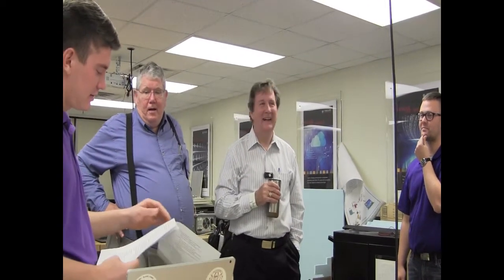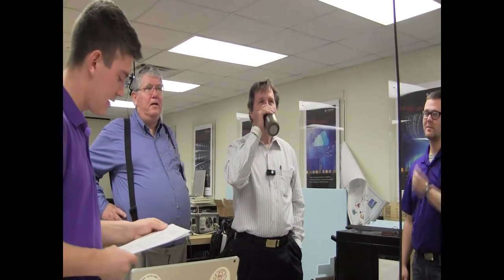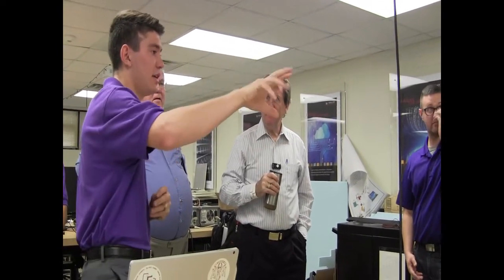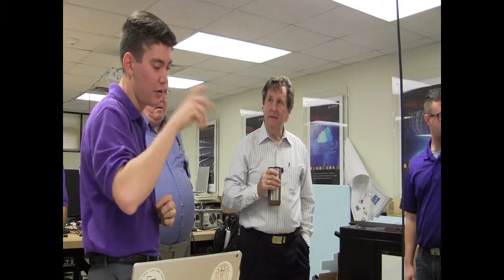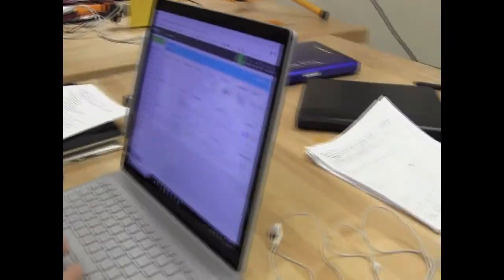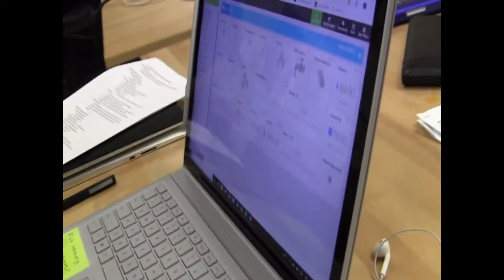So that's test 9. Test 10 is testing the ambient light sensors in room number 1. What we're going to do is, the room currently has the lights off and the blinds closed. We're going to take note of the reading where it stands, which is at 9 lux. And then I'm going to open the blinds and keep the lights off, and you're going to watch the lux